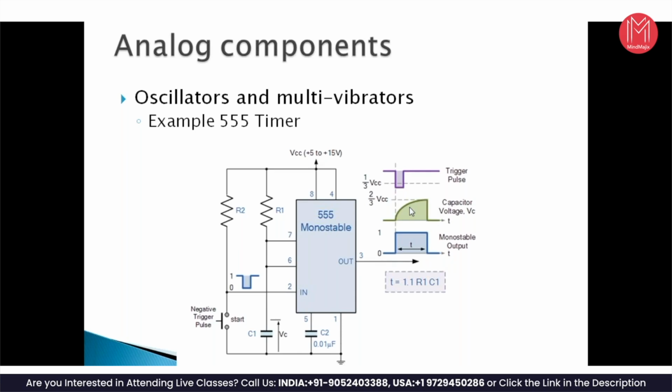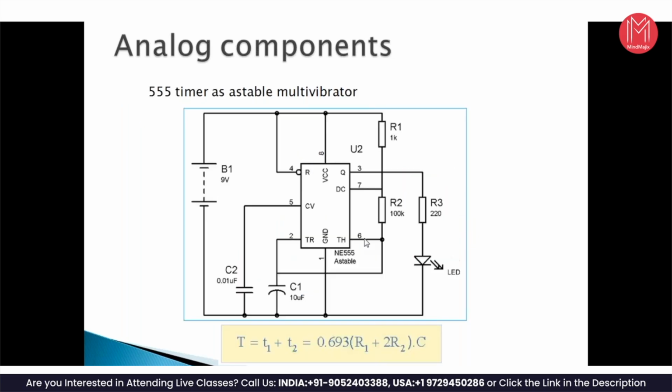So this is nothing but a monostable multivibrator, typically used in reset circuits. We apply it when we want the reset of the microcontroller to stay for a minimum duration. This is something that we have done in basic electronics, so hopefully this will serve as a revisit.